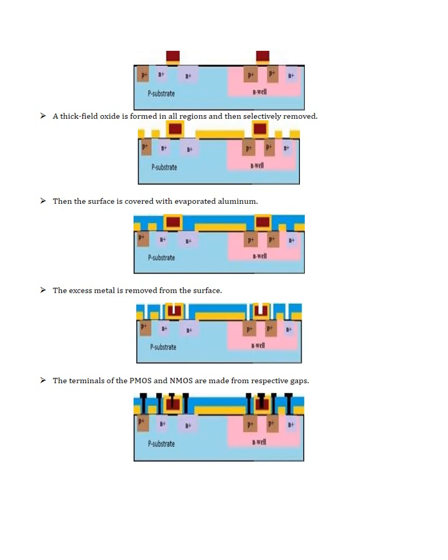Then P-type doping will be done. Then insulating gate oxide will be deposited. After that, contacts are created, because now the NMOS and PMOS are created. You can see in the pink region and in the blue region there are now two transistors.